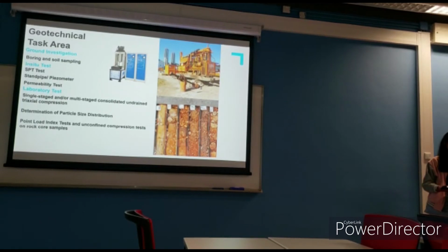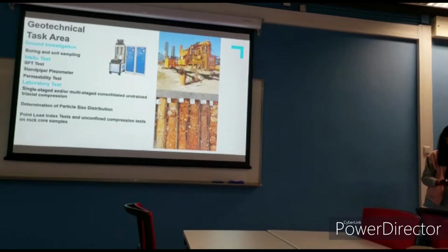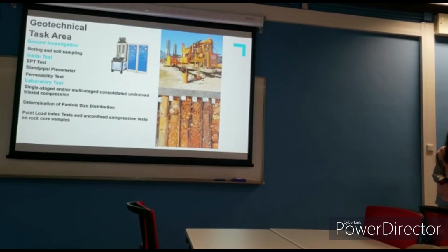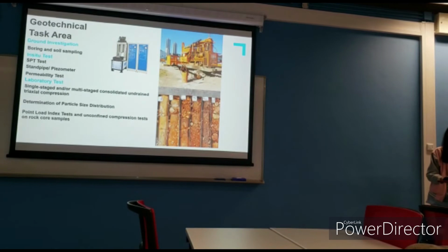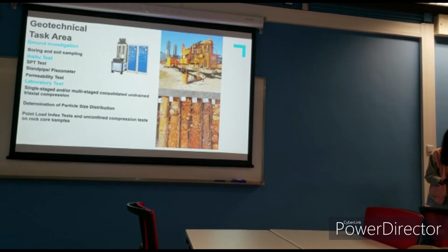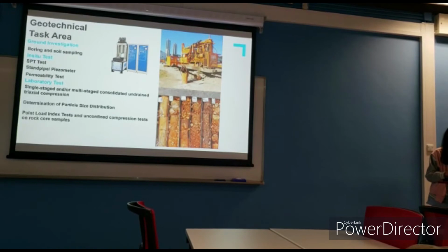The vertical borehole will have sampling at 2 meter intervals. Also, a piezometer or standpipe should be installed to verify the groundwater condition. Also, we should carry out the permeability test to verify the permeability parameter of the soil.